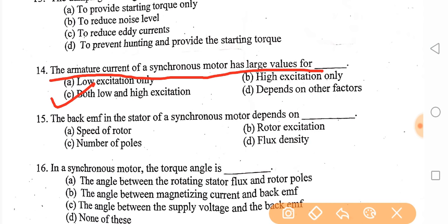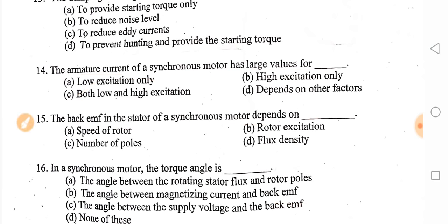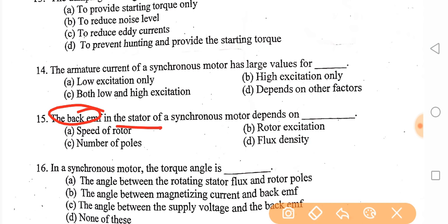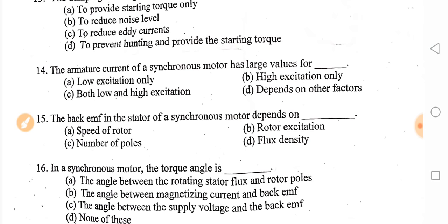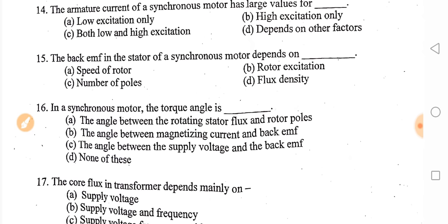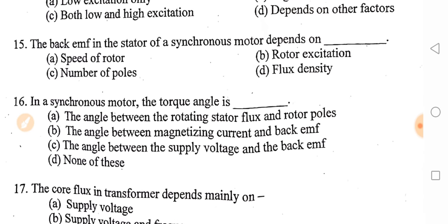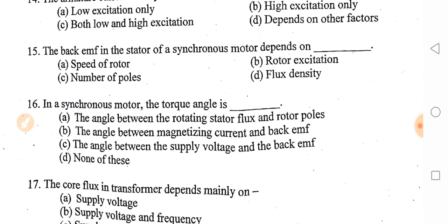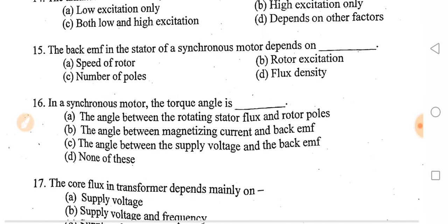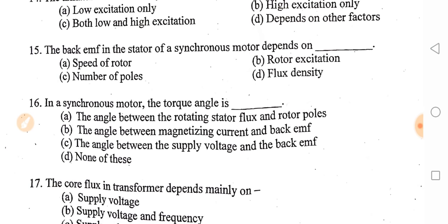Next question is, the back EMF in the stator of a synchronous motor depends on. So the back EMF in the stator of a synchronous motor depends on what? It depends on rotor excitation. How much excitation is given to the rotor will affect the back EMF in the stator, and that much back EMF will be produced in the stator of a synchronous motor.